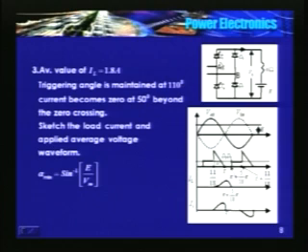Here T1 turns off because we have a common cathode configuration, out of which one of them is the diode. So the moment B potential becomes higher than A, D3 starts conducting, which turns off T1.